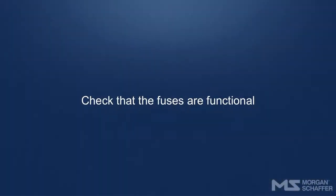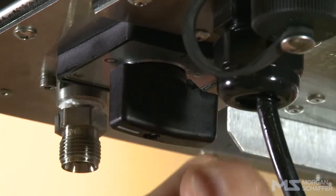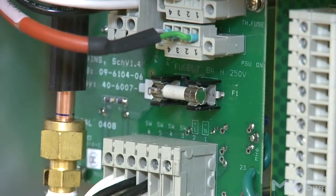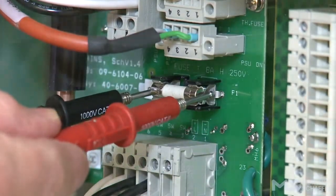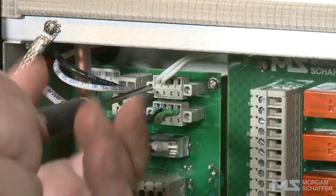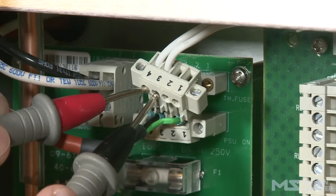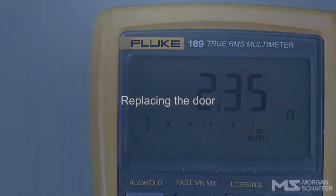Check that the fuses are functional. Turn off the Calisto and close its circuit breaker. Check the continuity of the fuse, F1, using a multimeter. Connect a multimeter between pins 3 and 4 of the J2 connector. There must be continuity between the pins. If the fuses are defective, they must be replaced.